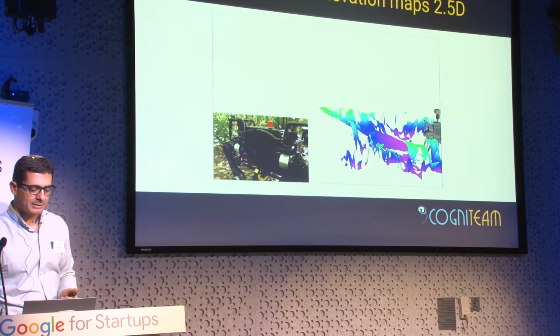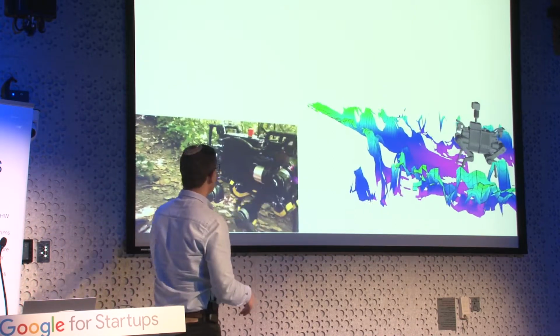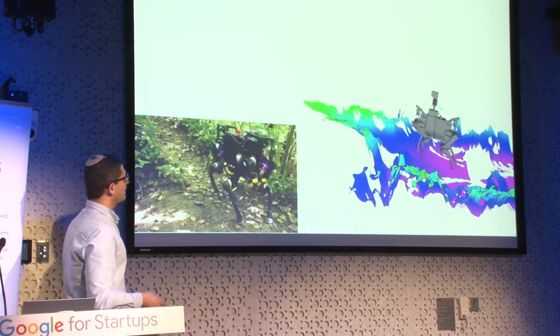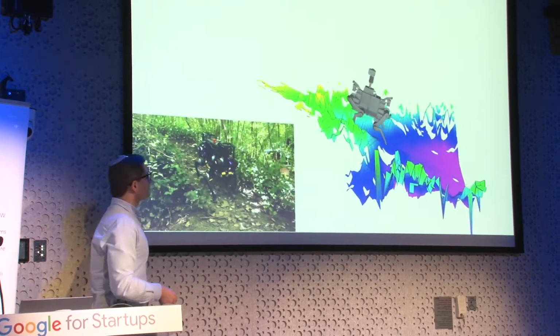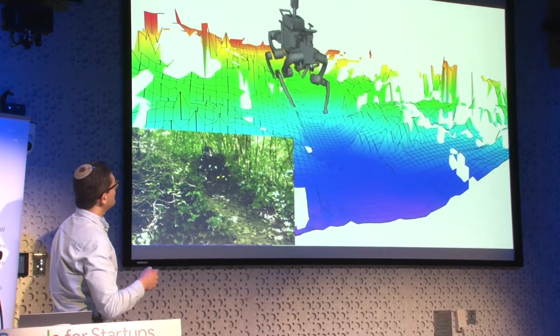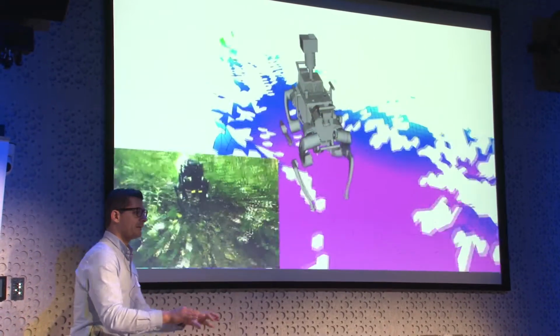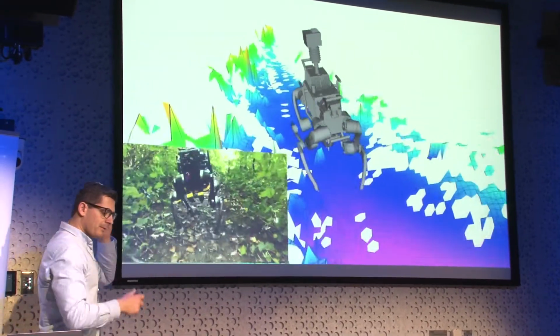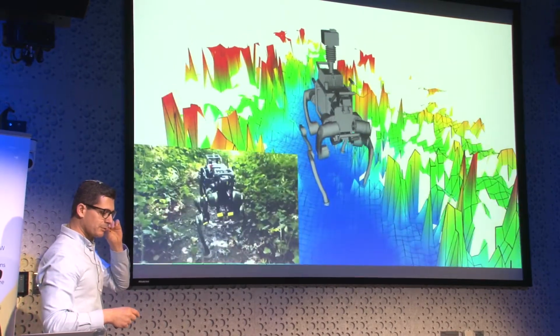And here you can see an example, not for SLAM, but in real time using an elevation map. You see this robot moves with 2 rotating lidars here and here, and it moves, and see that the elevation map here, what it sees, it understands, I can go, I can't, and builds this map. And 2.5D is actually in practice very useful as a map.